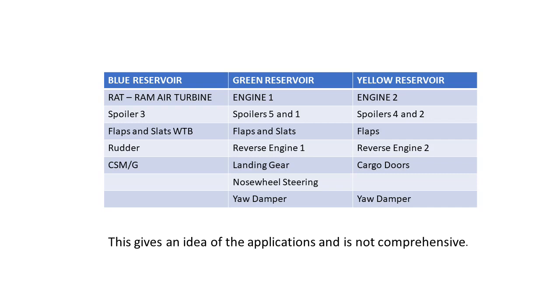One hydraulic compartment is the main landing gear compartment, which contains the components of the green system. Okay, that's your left side. The other 2 hydraulic compartments, your blue and yellow, are forward of the main landing gear compartment, the left and right belly fairing respectively. The systems are designed to be separated hydraulically. This allows for the systems to continue in case one of them fails.